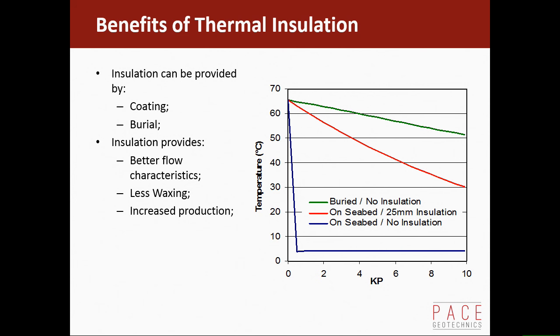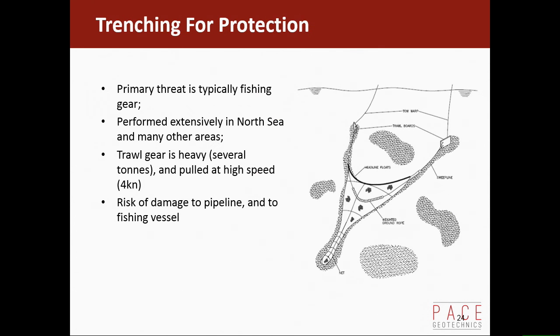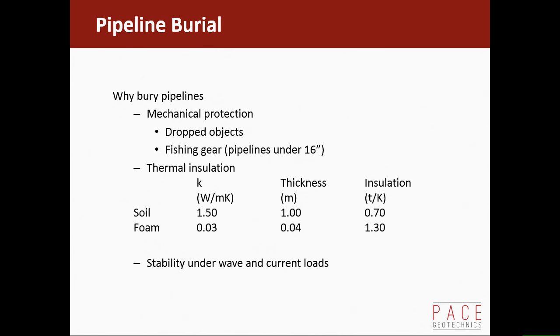Yeah, but in the previous slide, insulation has less conductivity, so there was... Lower conductivity, higher resistivity reduces the heat loss. Do you see? Okay. So it depends on how you express it. Higher conductivity there, but lower actual heat loss. The conductivity and thermal resistivity are just the inverse of each other.